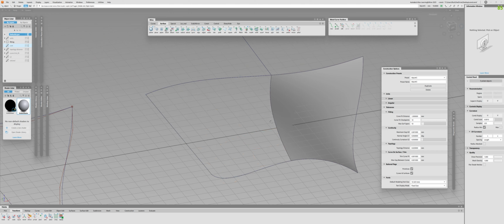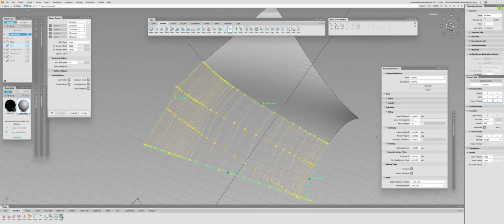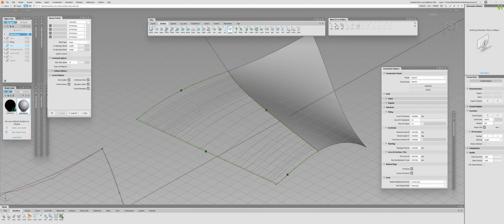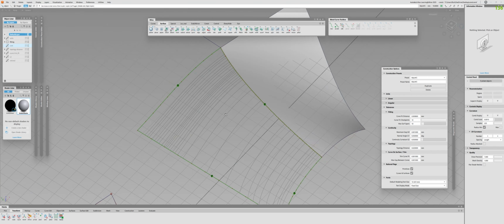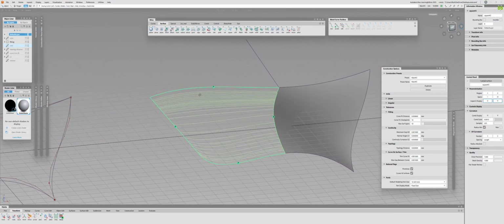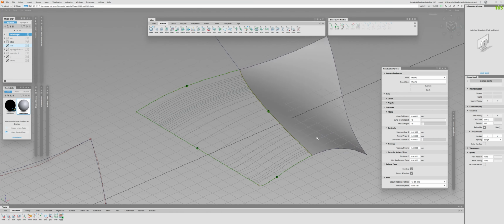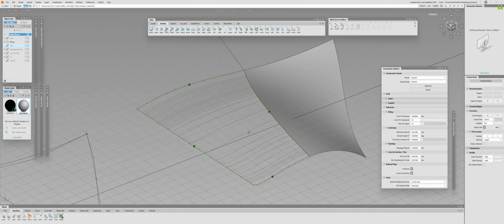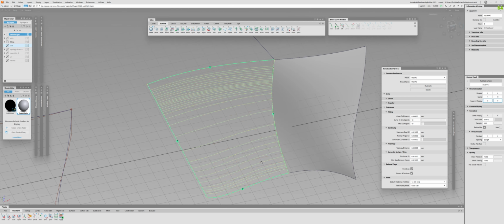If I, on the other hand, tighten the tolerance back and then create the square again, look how much more complex it becomes. Once again, I'm not asking Alias to create a specific surface, I will do it a little bit later. So I'm not using explicit control and am leaving Alias to do the work. And it did, but how many spans does it bring me? It brings me 30 spans. Well, that's a lot. So obviously we can do it better and achieve position, but this is the automatic process, and just based on this curve fit distance, Alias was able to create this.